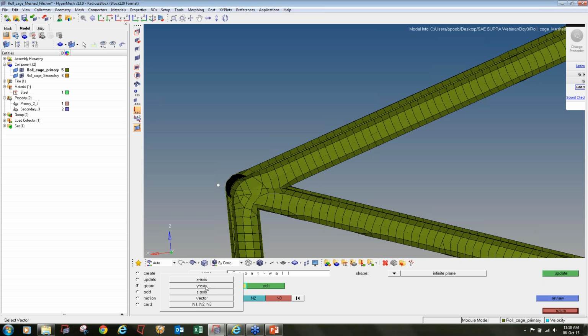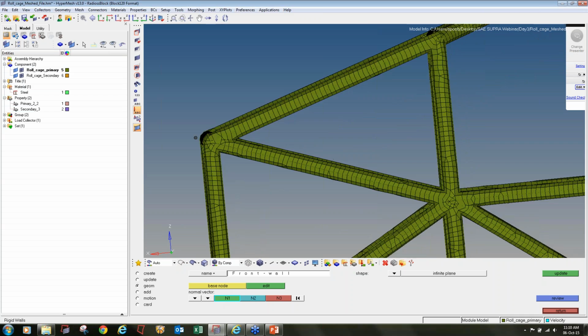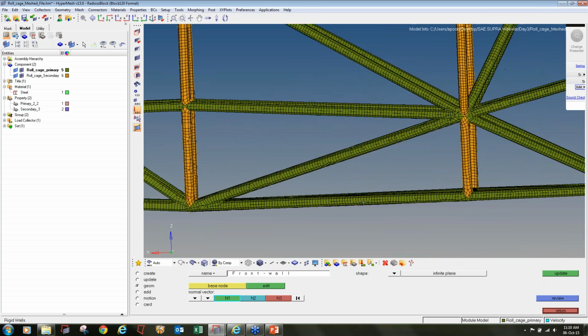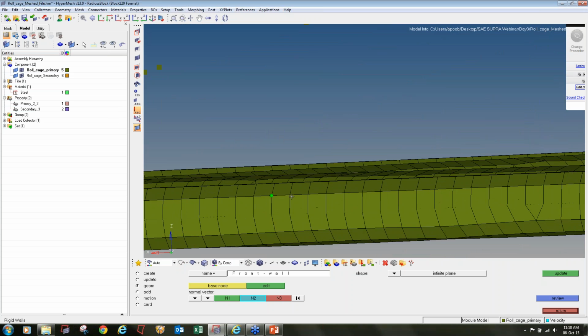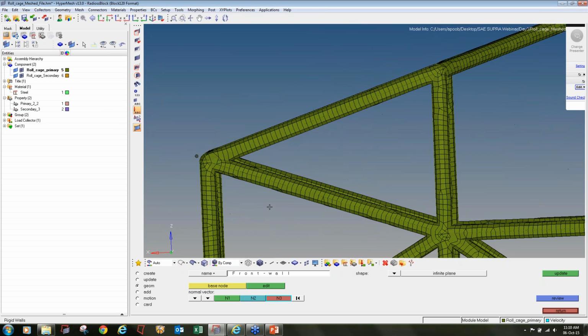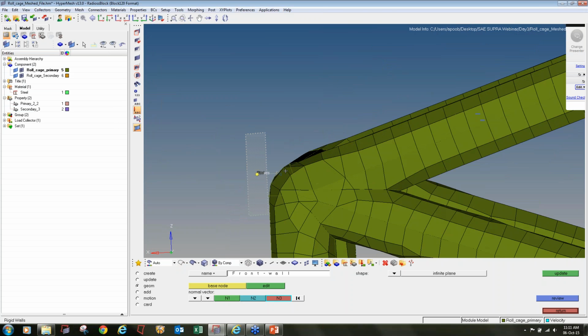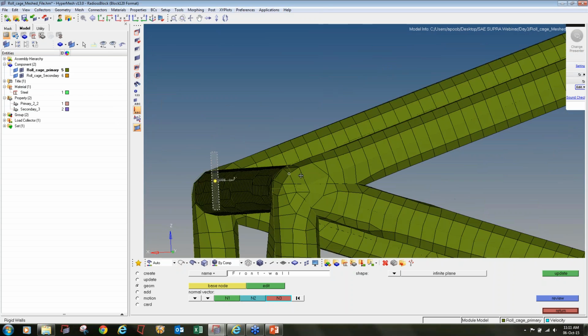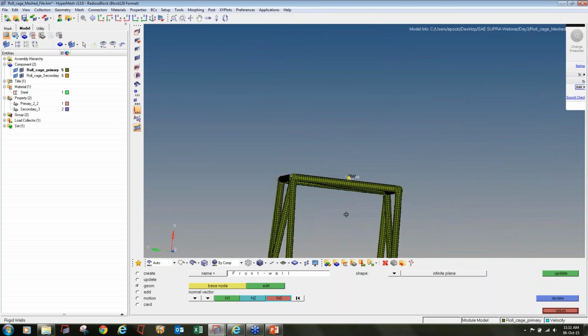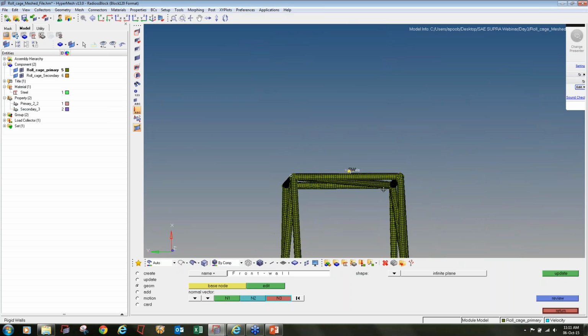So you can see it is a bit away, and define the normal vector. As you can see, I cannot use XYZ because it will take the positive direction. So I will use N1, N2 to define the direction. I will select any two nodes which will define the direction of the wall. The direction of the wall has to be opposite to the direction of velocity. So you can see my direction of the wall is in this direction.